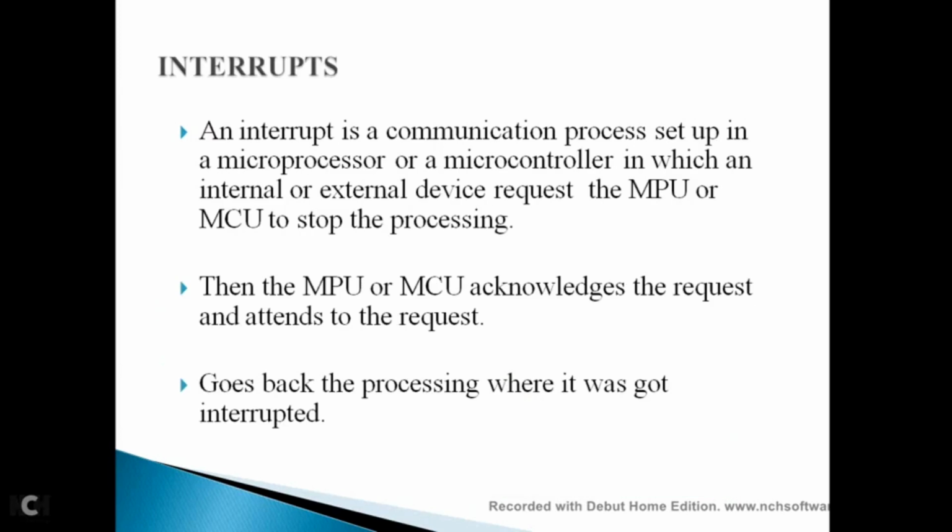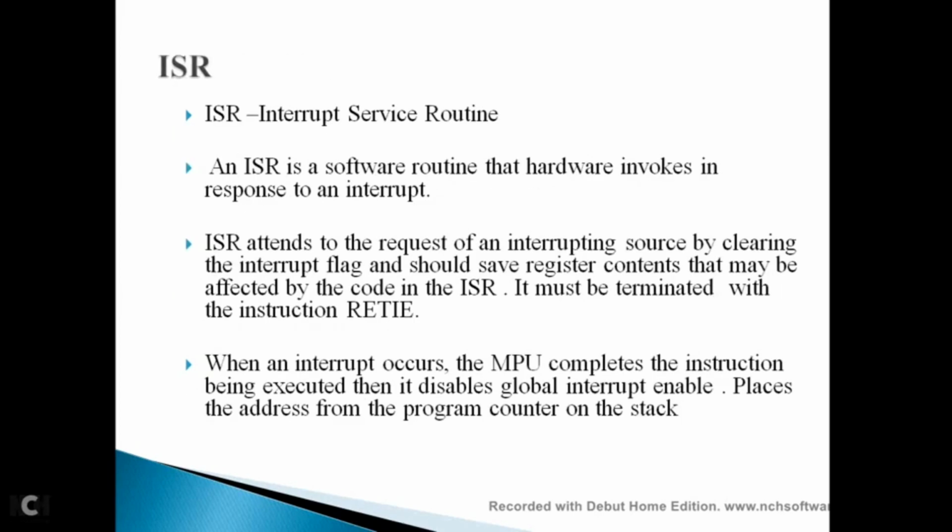Interrupt. An interrupt is a communication process set up in a microprocessor or a microcontroller in which an internal or external device requests the MPU or MCU to stop processing. Then the MPU or MCU acknowledges the request and attends to it. ISR, Interrupt Service Routine.